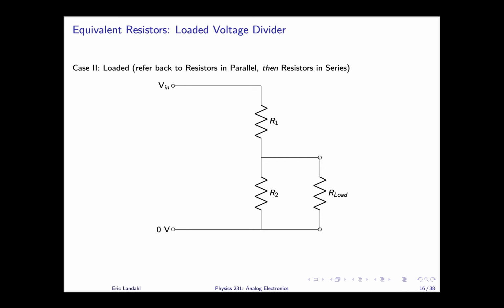Now that's a lot of effort, and I'll be giving you some examples on how to do it. But the reason to go through the exercise at least once or twice is to understand the importance of this load resistor and how adding a load resistor changes the way the circuit would have behaved otherwise. And that's a really important thing when you're building modular electronics and hoping to just go and use patch cords to plug in and out loads. You want to know, are they going to change what was going on upstream or not?